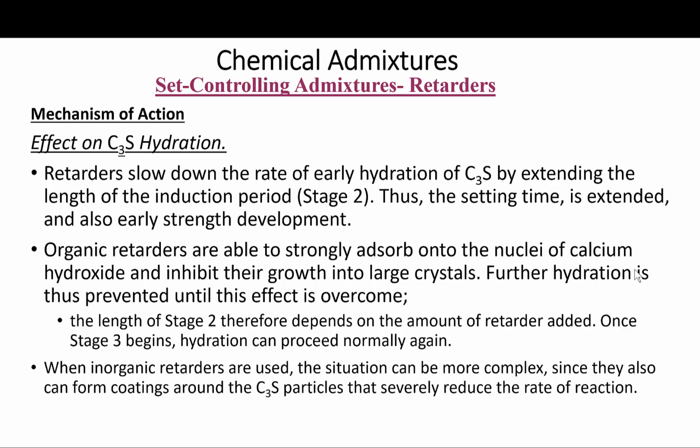So measures are taken in the event of unanticipated delays to avoid the hardening of the concrete in the truck, when it becomes too expensive to clean it. Also, carbonated beverages will be even more effective, since they contain phosphoric or citric acids as well as sugars, all of which are retarders.